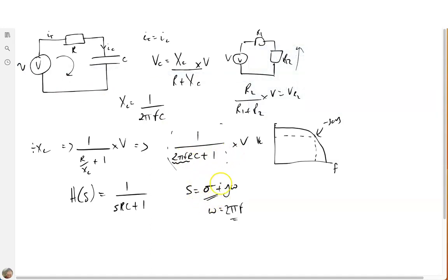More on this later, but when we're analysing these circuits in the basic form, this equation here, if you want to derive the output voltage at a particular frequency, is the one I've highlighted. If you wanted to find the absolute magnitude, we've got a difficulty here. This is the imaginary impedance, because it's formed using this capacitor, and this R is essentially the real part of the number. So we could say this is 1 plus jRC.